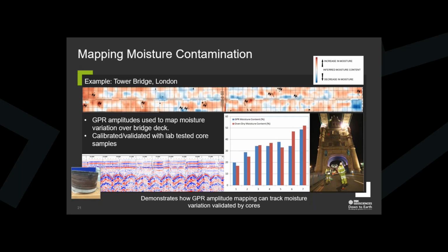So we knew then that any apparent thicknesses in the GPR data must have been due to the moisture within that wood, because the moisture affected the electrical properties of the wood and caused the GPR wave to travel more slowly, which increased the two-way travel time and essentially made the wood look a lot thicker.